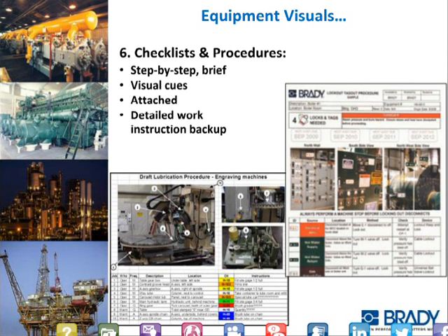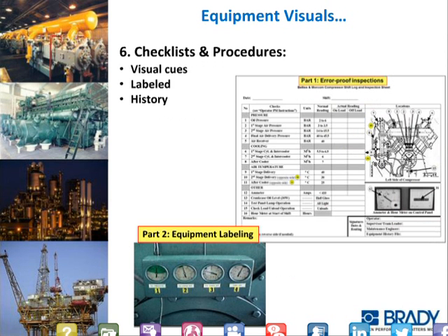As we look at visual procedures, this is a compressor, a blow molding compressor, for the blue bottles for soft drinks. And the compressor manufacturer had a warranty requirement that says for the first year we need to have pressure readings, temperature readings, and so on. So we took the reading compressor log sheet from the manufacturer and modified it, and that's the diagram you see in the center part of the slide. We divided up the inspection points by what you're looking at: temperatures, pressures, and so on, amperages and hours. We put in the type of reading, what the normal range was, and then a place to write